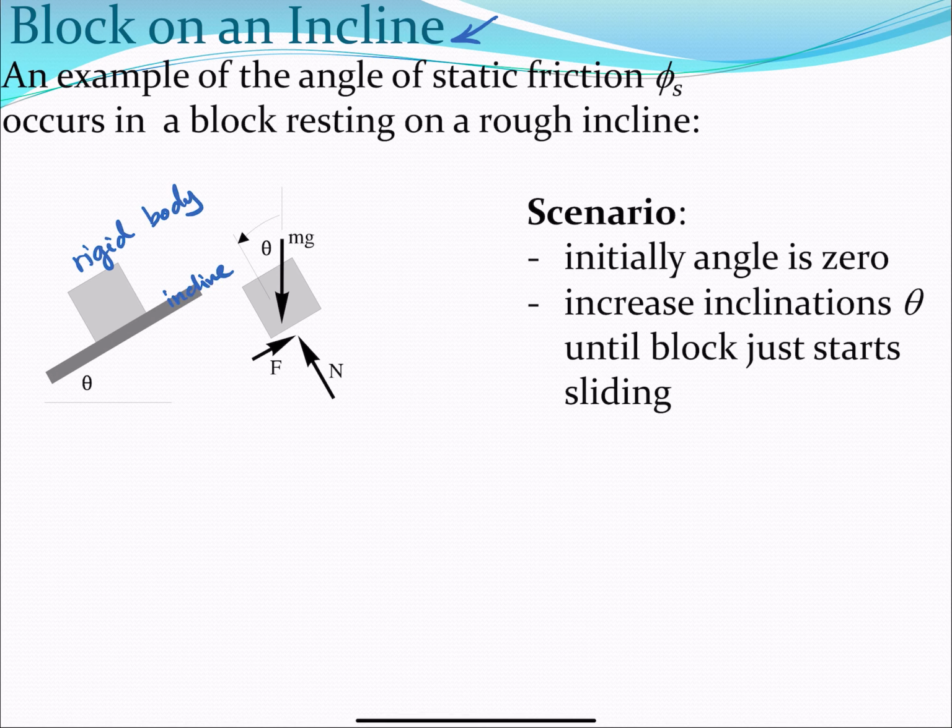And if you wanted, you could obtain the friction coefficient. You don't need a specialized machine or to measure the normal force or the weight in order to determine the friction coefficient. We can do it using simple free body diagrams. So I take my rigid body, and I write the forces acting on it.